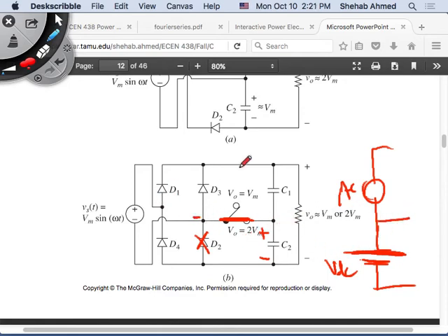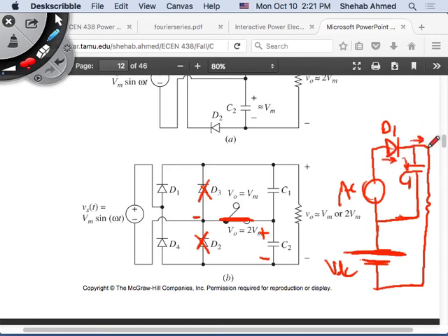Your other circuit is this diode D1, right? You're talking about the positive half cycle, right? Yeah. Then I have diode D1, and this other diode will never conduct, right? Because I have a positive voltage here, and then it goes through capacitor C1 and my load. Current is coming from the source to charge my capacitor as well as going through the load.